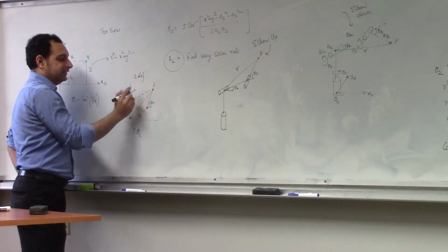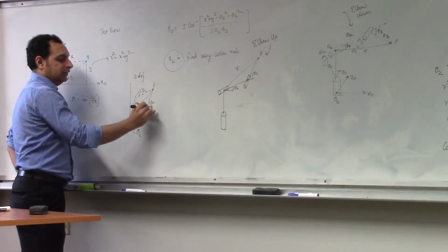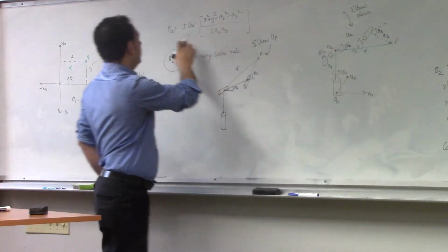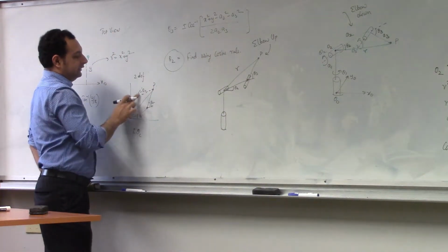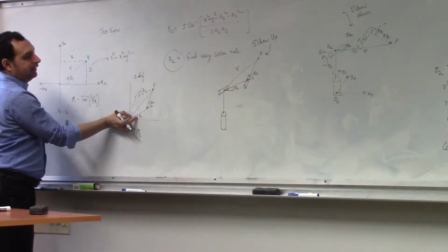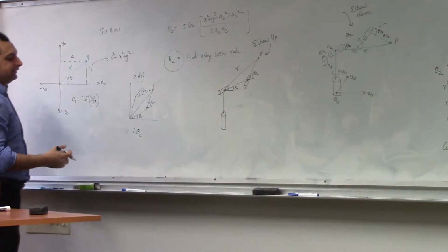So this is minus theta 2, and this is plus theta 2. In this case, because the last joint is theta 3, this will be plus or minus theta 3. You'll get exactly like this. I'll go up, I'll go down. So the only thing is, here you found theta 1 like this, here you have to find theta 2. So do the same exact steps.